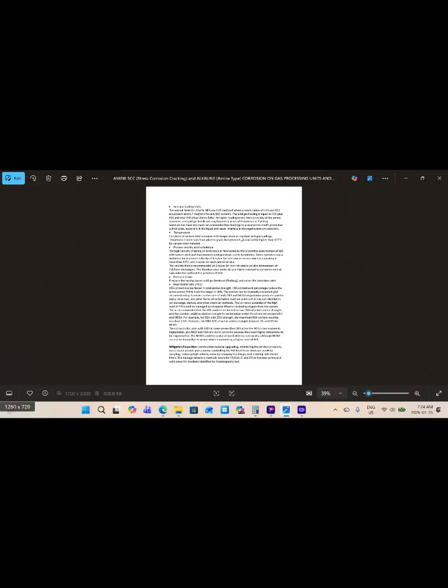At a higher loading level, the corrosivity of the amine increases and acid gas breakout may happen, increasing the turbulence of the flashing. Some amines have a minimum recommended lean loading to preserve the steel's protective sulfide scale, especially at the liquid and vapor interface in the regenerator and reboiler, as already discussed in the process flow diagram.